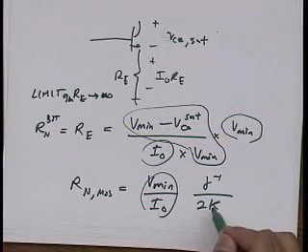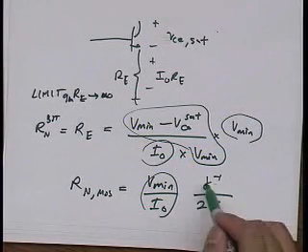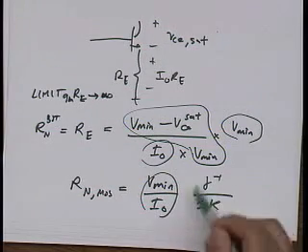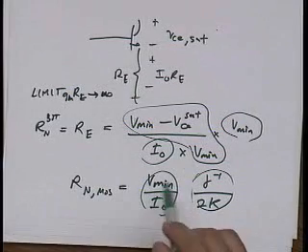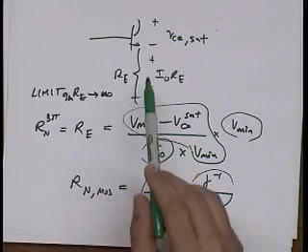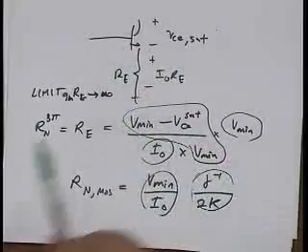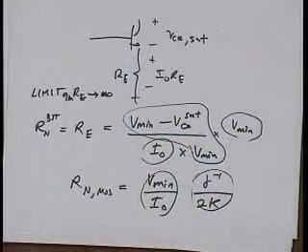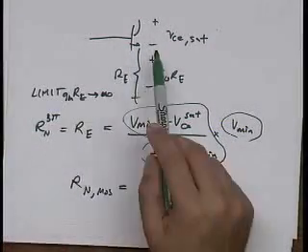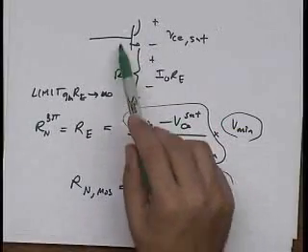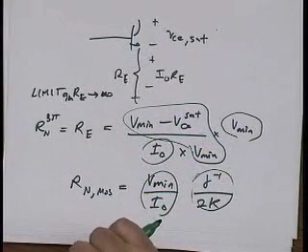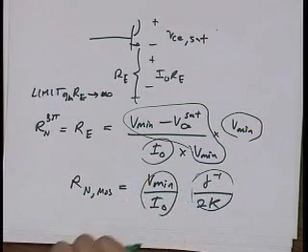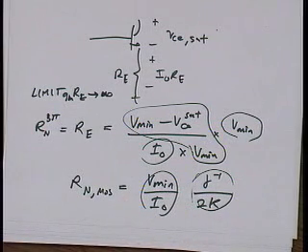If I look at this here, let's say gamma is on the order of 1, just to make things simple, and let's say k is 1, so this is also on the order of unity. So to first order, the Rn of a MOS device is the same that you'd get in a bipolar device that's been heavily degenerated. So to first order, there is no benefit in using a bipolar device. You're not getting any win, because really you're degenerating the gain away by using this large resistor in the first place to minimize the noise. Is that argument clear to everybody? Questions?